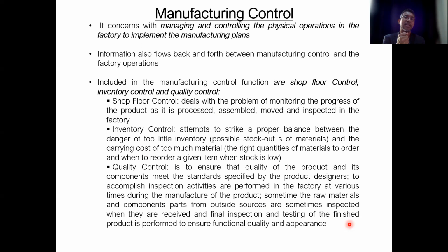If not, that becomes an electric short circuit or a malfunction of the alternator, because the IC regulator controls the alternator itself.